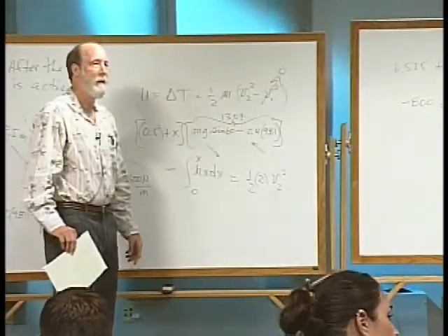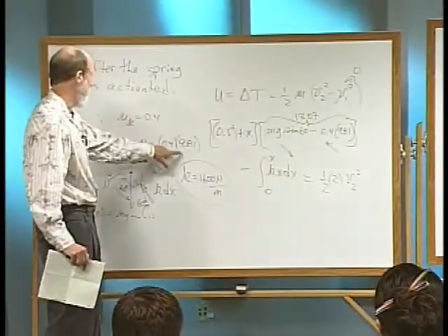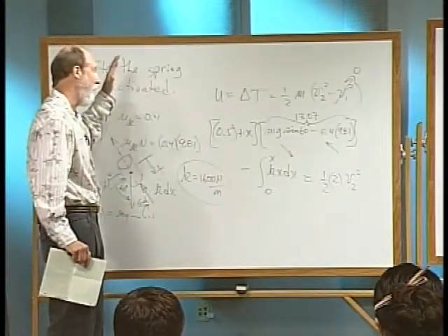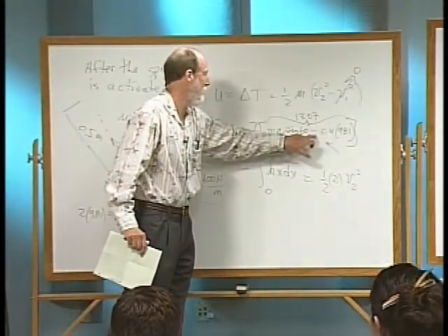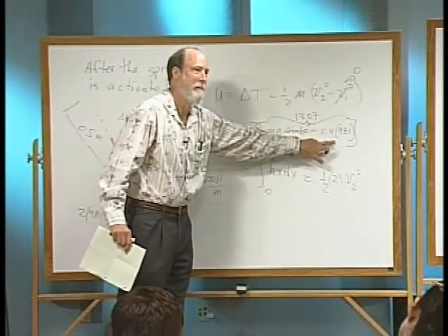So where are we accounting for the energy lost from the system due to friction? Now that's built into the work done by this friction force throughout the entire travel distance. See, that's embodied right here in that negative term, negative work done, while it's engaged with the spring.